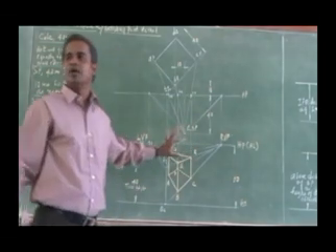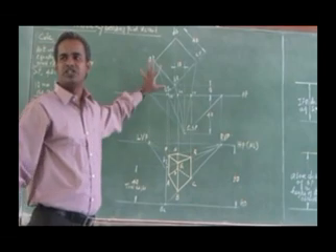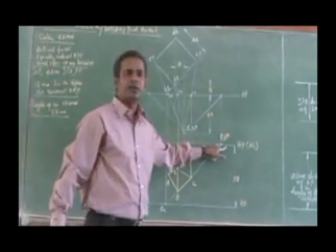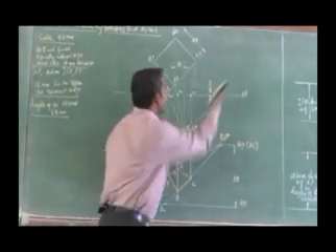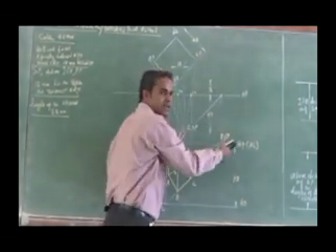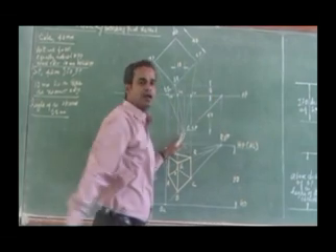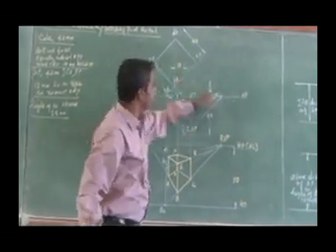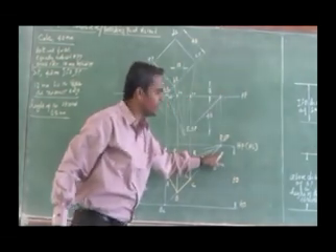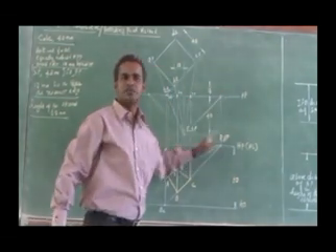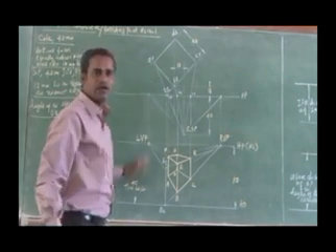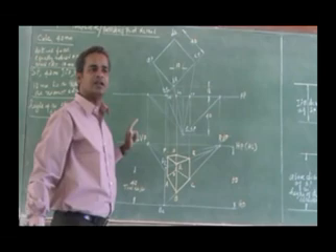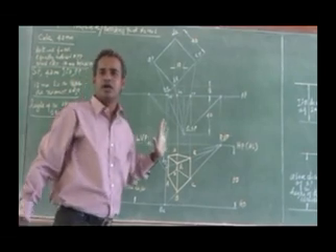So this is the two-point perspective vanishing point method. Right? The vanishing point carefully you have to obtain from station point parallel to one face to the right side. I have to draw a parallel line to the picture plane. So draw a parallel line to this face, it will meet the picture plane. By dropping that to the horizontal line, that is my right vanishing point. Similarly, left vanishing point, parallel to this face and dropping to the horizontal line, I will get left vanishing point. Right, is it clear? Have any clarification?